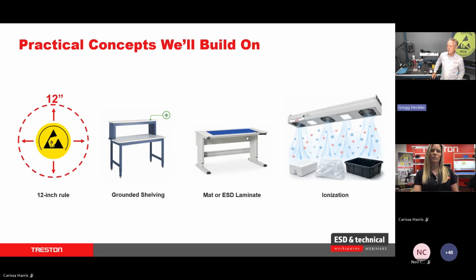Right. So if you are using what we call process essential insulators, remember we discussed that, things that have to be used. Those are connectors, your product enclosure, things like that, other components that are close by. Like one of our continuous monitors, we use a speaker in there. So when the monitor alarms, you can hear an alarm. Well, that thing generates 3,000 or 4,000 volts. So that would be something that I need an ionizer to neutralize.